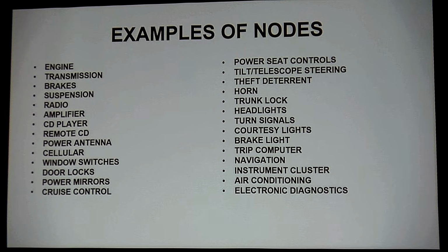So once you start to think about this more clearly, each one of you needs to think about what you are working on. I was just at a shop where this guy was so confused because he had high-speed wires going in. They were for the steering column, you know, the steering position. They're not for the wipers. The wipers are on a very low LIN bus. So he's looking at the wrong bus to try to figure out his problem. I want you guys to not make that mistake.